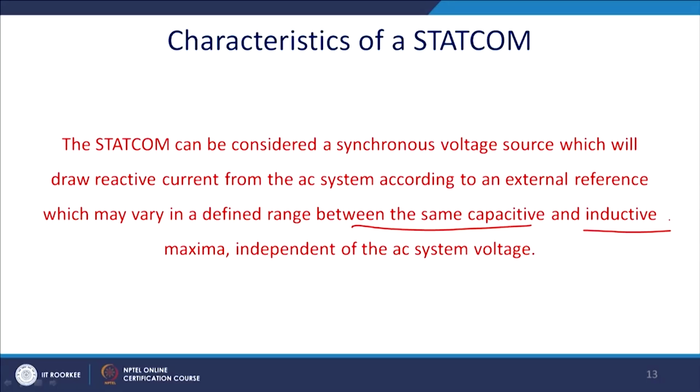So, it is a very effective tool when a sag occurs. We shall see in our next class that the reactive power compensating capability decreases in the case of the SVC in transient and other conditions, but the Statcom can compensate the reactive power very well even in a disturbed system.